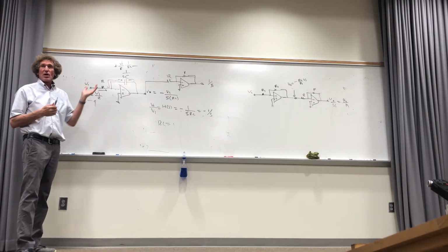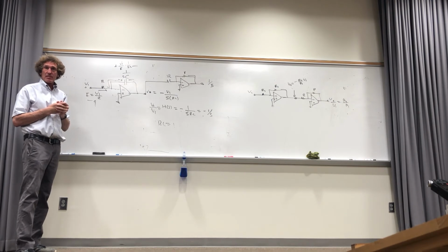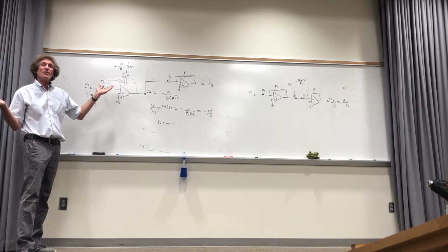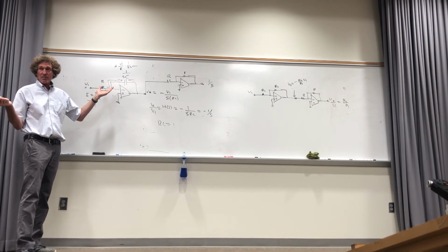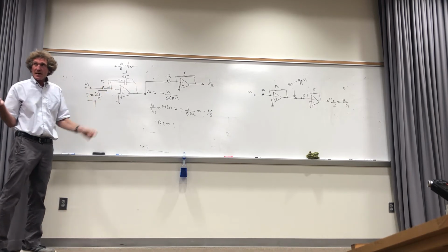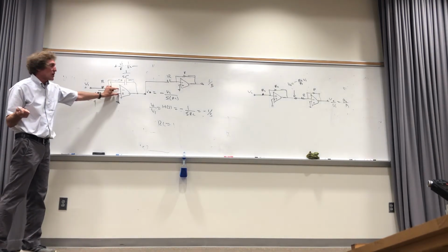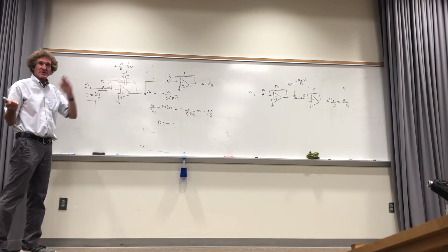Now, some of you are thinking, well, what could you possibly ask me? I could ask you to do a block diagram representation, the way I just showed you, and maybe implement a part of it, something like that. But you all follow me on this one, class? It's not that difficult, but you have to know what you're doing. And remember with operational amplifiers, with analysis, no voltage across the inputs, no current into it.